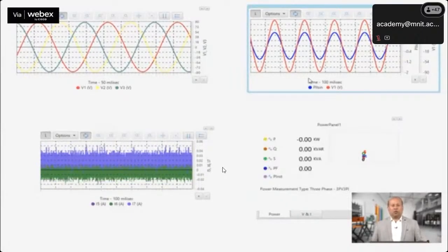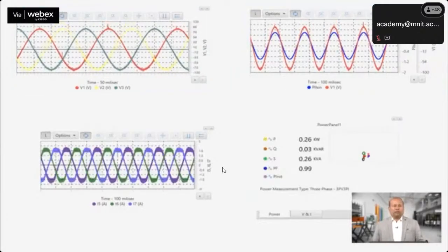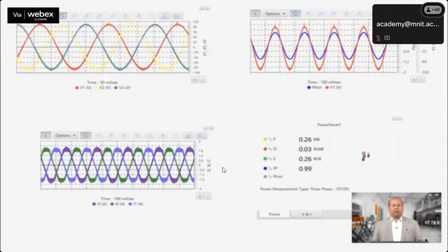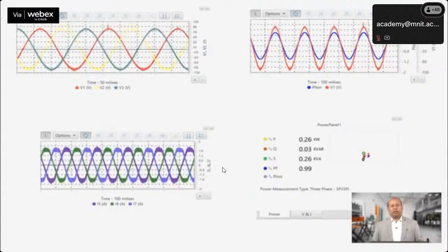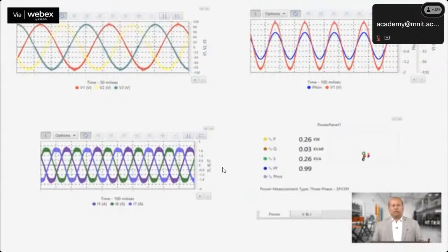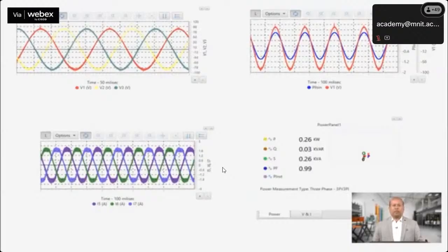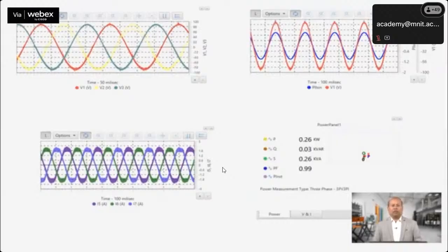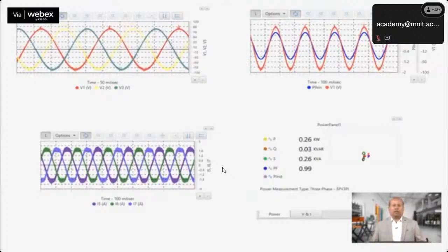After this setup, we will enable the PWM pulses sent by the WAVECT controller to the BESS converter. Enabling the PWM pulses will feed the Id reference and Iq reference, that is the real power and reactive power, as determined by the peak energy management and voltage profile algorithms that will run on the RTDS platform.